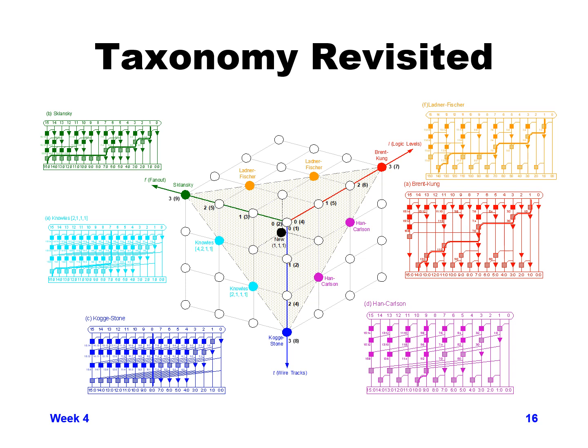And depending on what you're looking for, you can balance your adder to try and get some delay versus wire tracks versus fan out, and determine what works best for your particular application and choose the adder design that works best for you. And so once you choose what point you might want to look at, then you can go research that adder design in detail and figure out how to implement it in your situation.